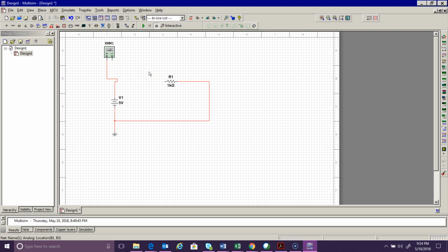If you think about current as the flow of the electrons, then you have to get in the flow of electrons to be able to measure the flow of electrons. So that was what we do with the meter here. As we connect it, we make it part of the flow of the circuit, and then we can measure the current.